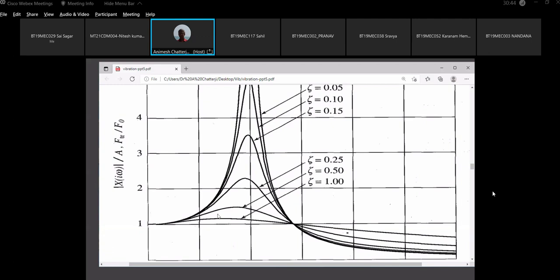I had asked you that you have gone to the market. The excitation frequency is 25 hertz. How would you select an isolator stiffness? And how much you will select? This question was asked on Sunday. Answer? Sir, K will be 12 giganewton per meter and R will come out to be 1.433.